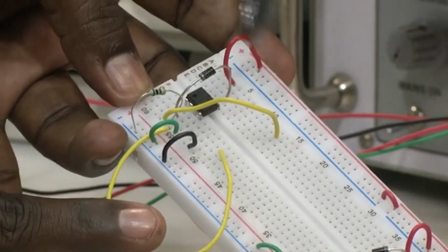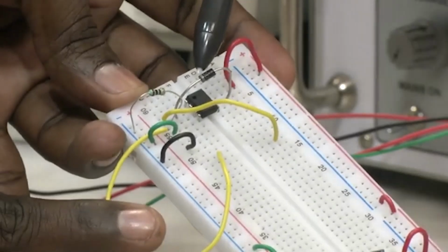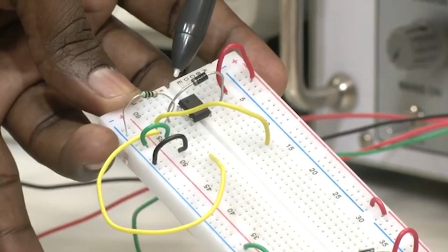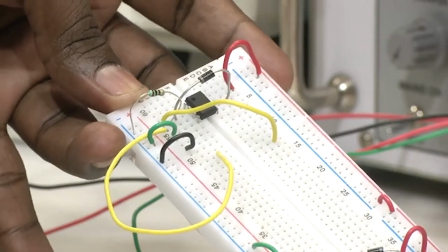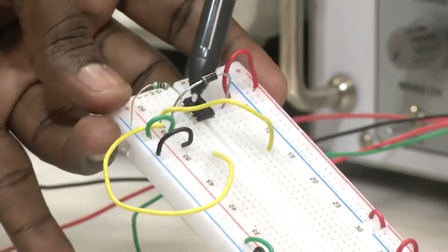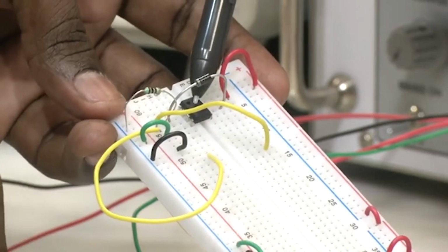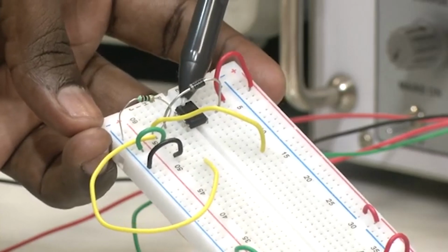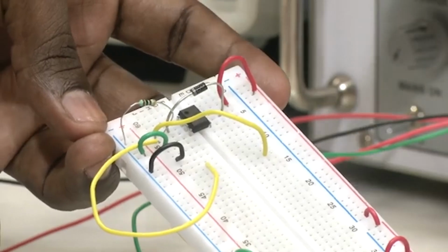He is holding the breadboard and you can see very clearly there is an anode which is this one, and the silver one is the cathode. Then we have a load resistor RL, and a buffer which will act as a voltage follower when this diode is on. When the diode is off, it will not conduct, and it will not work as a voltage follower.